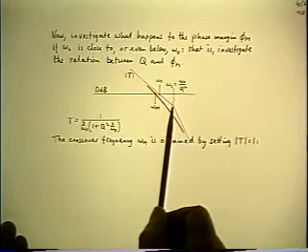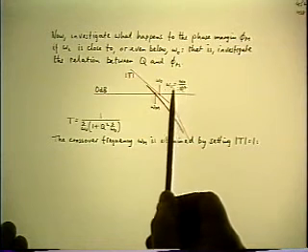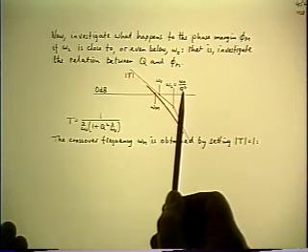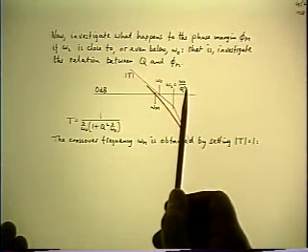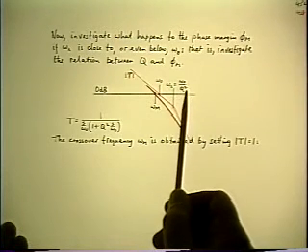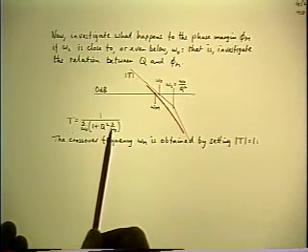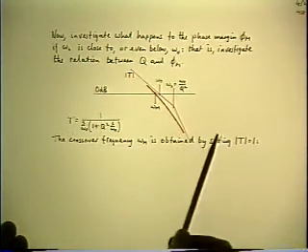Instead of omega 2 being the variable, now Q is the variable, which we get by inverting the definition of the Q. Q was the root omega 0 over omega 2, which means inverting it, omega 2 is omega 0 over Q squared. So I've simply made the substitution in the formula for T. So Q is now the parameter.